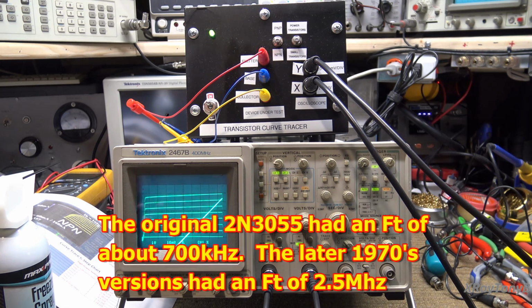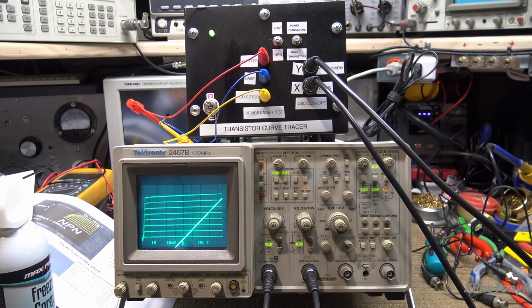And everybody that works on amplifiers is real familiar with the MJ series, the big TO-3 transistors, like the MJ21193, MJ21194, MJ 20-something or other. There's a whole bunch of them. All of them have transition frequencies somewhere between 2 and 4 megahertz, which is relatively low compared to some other transistors out there.